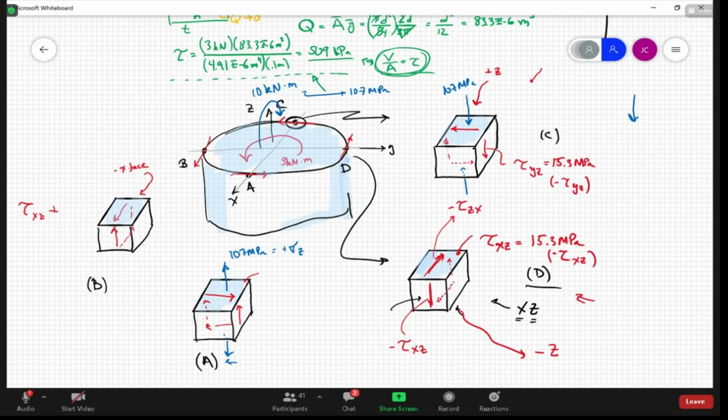It would have made the stress greater at point C because they would both be negative Z stresses and would add together. Whereas at point A it would be of a different sign, compressive, and subtract from that positive bending stress. Does that make sense?